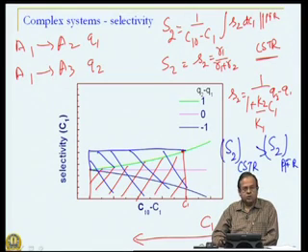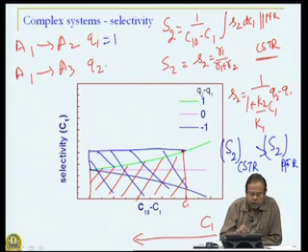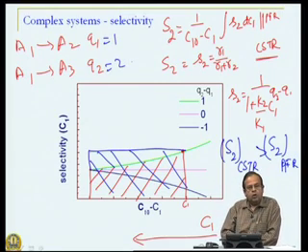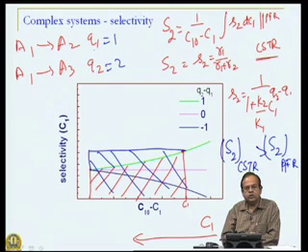But what about conversion? So, just let us put some numbers. Suppose Q1 is 1, Q2 is 2, we know that for power law kinetics with positive values of Q1 and Q2, conversion is always highest in plug flow reactor. We discussed that a few sessions back. That is because the concentration suddenly decreases in CSTR, whereas the decrease is gradual in plug flow reactor. So, conversions are better in plug flow reactor compared to CSTR.